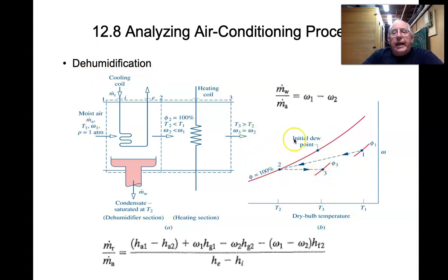We have to bring it down to a low enough temperature in order for the vapor to condense, but then it's actually too cold and we actually have to bring it back up in temperature and drop the relative humidity. And so in this region, this would be more comfortable to the person that is receiving that cool, drier airstream.